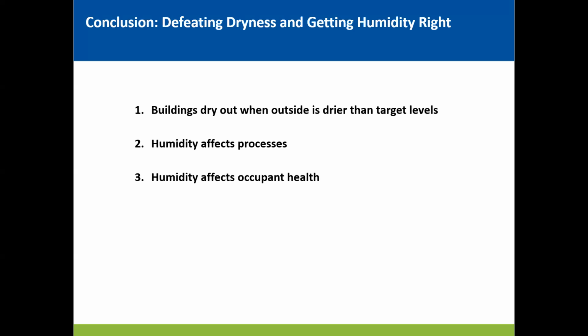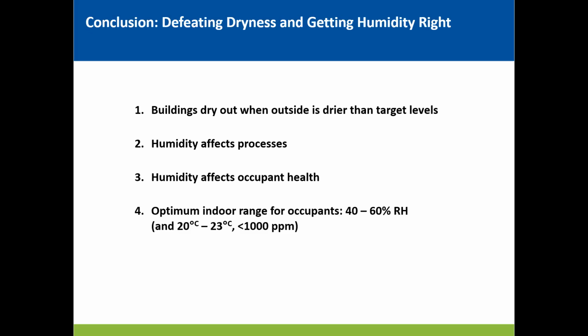Humidity has significant effects on the occupants in the building too. We talked about some of the indirect effects you can feel with your mouth, your nose, your eyes, skin. But we spent a lot of time talking about the important and the latest research that humidity actually has a significant impact on the health of the occupants. Dry environments will tend to promote more infectious particles lingering around for longer, while making your body more susceptible to it. And really, the key here is an optimal set of indoor conditions.